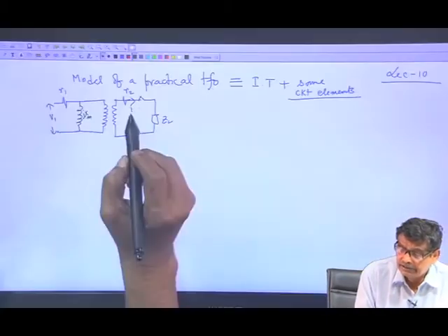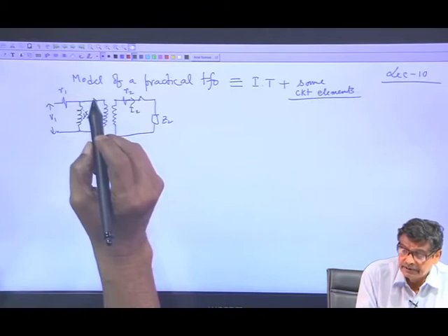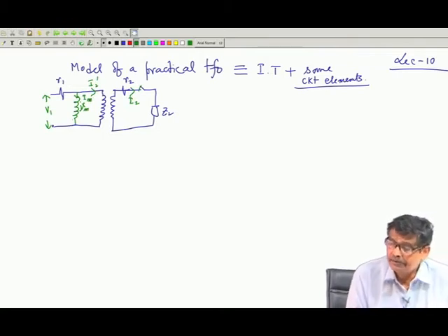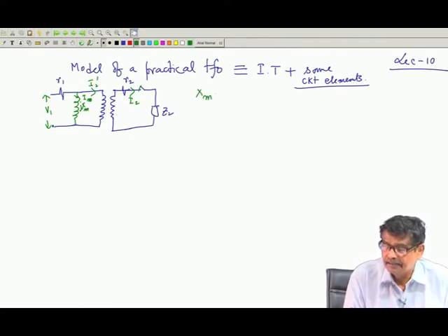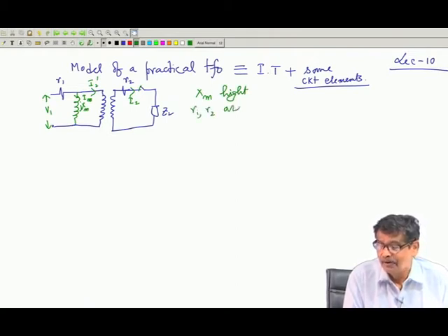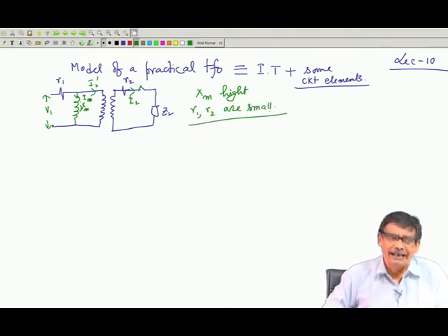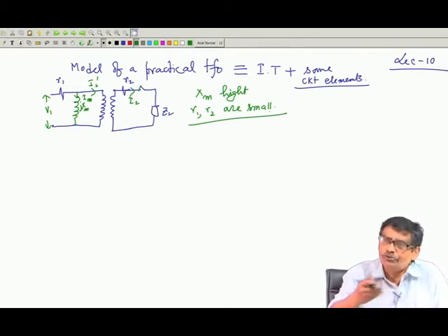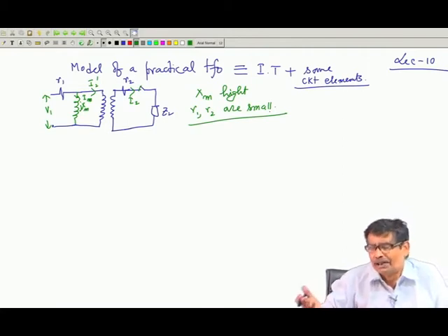When it is closed, it is I2, remember this is I2 dashed, and this is Im, the magnetizing current, which is very small, because Xm is high. Mind you, I write it here, Xm high, R1, R2 are small. That is why people do this while analyzing a practical transformer circuit. Apply the rules of the ideal transformer. Suppose you do not have any parameter values known, Xm, R1, R2.